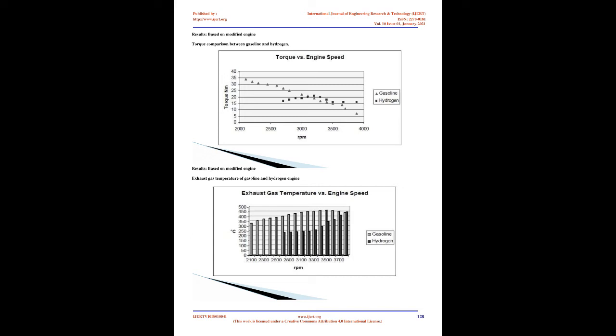Otto cycle, dual cycle. The heat that is evacuated during the cooling of a conventional engine's cylinder head is recovered in the 6-stroke engine by the air heating chamber surrounding the combustion chamber. As a result of this, less heat is wasted, which increases the thermal efficiency. After intake, air is compressed in the heating chamber and heated through 720 degrees of crankshaft angle, 360 of which are enclosed chamber, external combustion. The transfer of heat from the very thin walls of the combustion chamber to the air heating chambers lowers the temperature and pressure of the gases on expansion and exhaust, internal combustion.